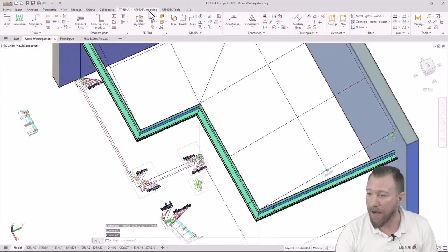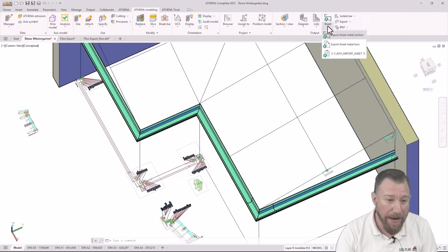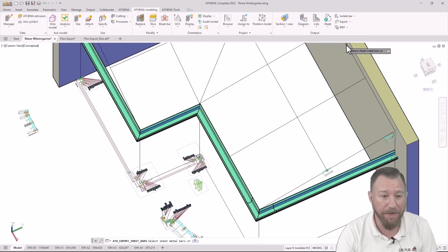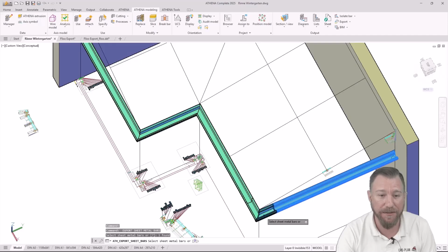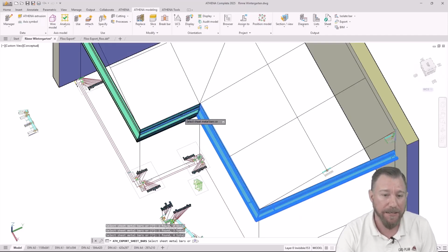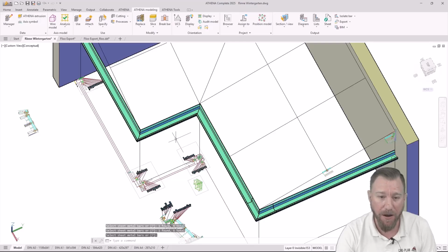So, we are done here, and now we will export the sheet metal parts and add more processings: a drain hole, a rectangular cutout in the flange, and modify the sheet directly. Using the gutter sheet metal example, I will show you a typical situation from practice on the right side, where the gutter meets the wall and will add an edge flange for a clean and stable termination.